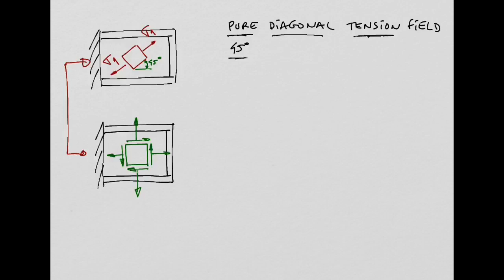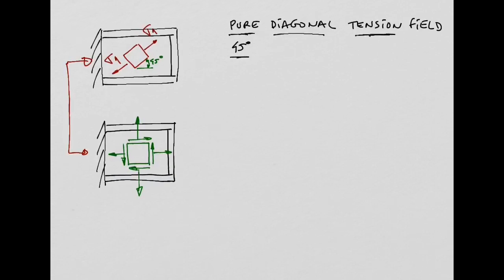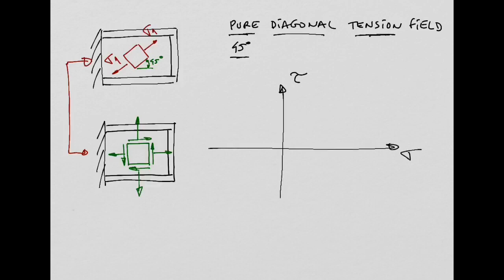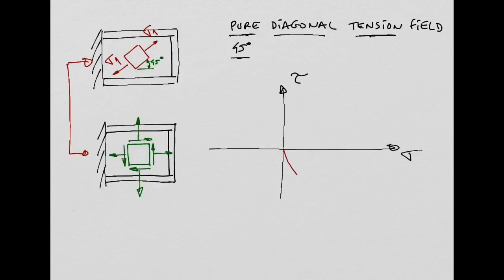So how do we do this stress transformation? What I suggest is, let's plot the Mohr circle for this sigma 1 again. We did it already, so let me just do it here again. So we have sigma axis, tau axis, yeah? We know that this Mohr circle in red needs to pass through the origin, yeah? So this point here is sigma 1.